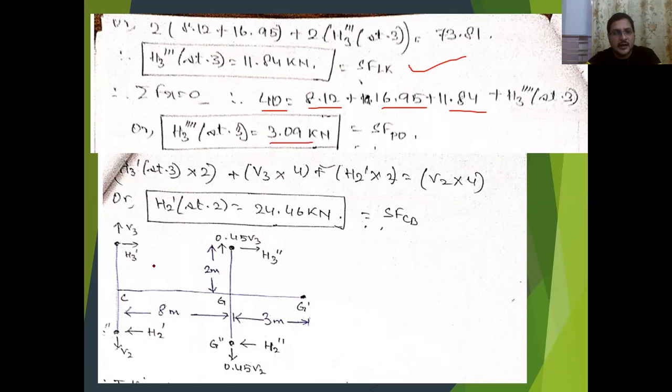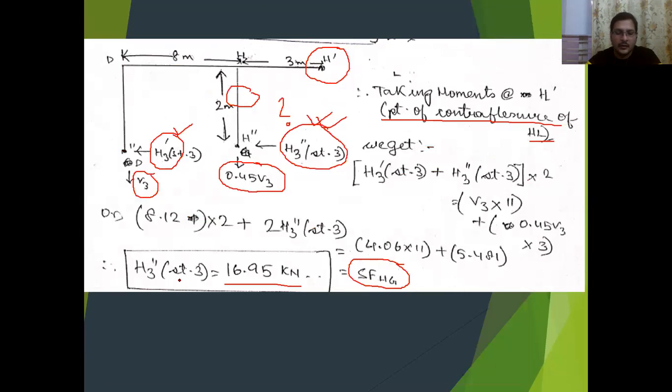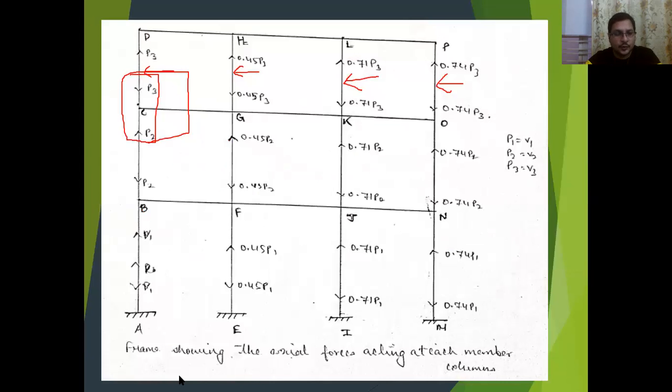Which are the forces? Now, just imagine if I take this portion, or if I erase this part, the shear forces which were acting from right to left, which were resisting the horizontal shear, when we consider this portion, that means we will cut the portions of columns, the point of contact flexure of the column of the above floor, the connecting floor, and also the column of the connecting floor, which is second.